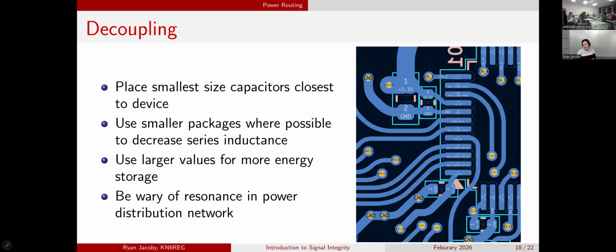Actually, could be quite a large fluctuation, but a little burst of current that now has to be consumed extra that the part was not consuming before. And then, if we have a really fast digital interface doing that a couple million times a second, that can cause a bunch of fluctuations in the voltage on those lines.